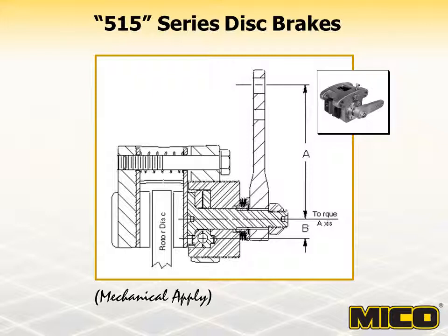This brake does not provide for automatic lining adjustment to compensate for lining wear. In addition to the fixed mechanical advantage provided by the cam plates, the lever also provides mechanical advantage. The maximum allowable clamping force of this brake is attained when 330 pounds lever pull is applied at the outside hole of the lever or 420 pounds to the inside hole.